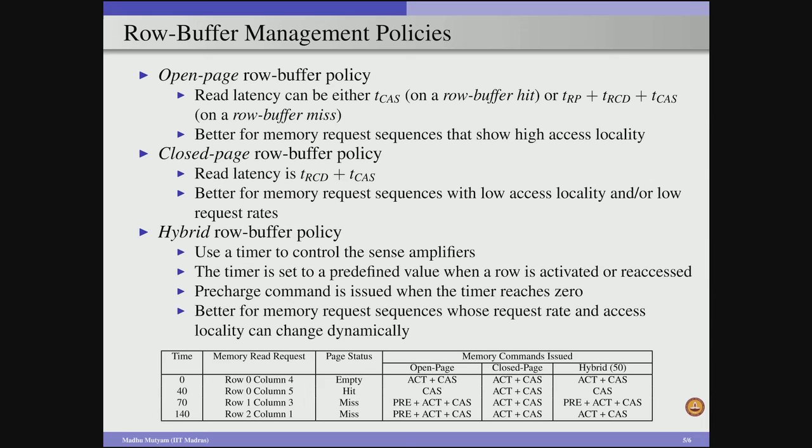In the case of the closed page policy, because the page status is empty, again I have to go for ACT and CAS, and similarly in the case of hybrid policy also, for my initial request I have to go for ACT and CAS. So effectively, since the page status is empty, in all these 3 policies, for the first request I incur the same number of memory commands.